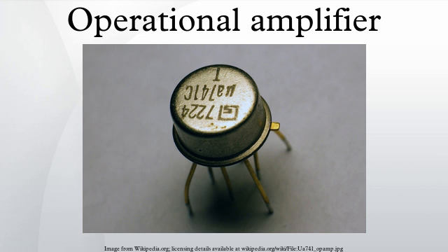The μA741 was extremely similar to the LM101 except that Fairchild's facilities allowed them to include a 30 pF compensation capacitor inside the chip instead of requiring external compensation. This simple difference has made the 741 the canonical op-amp and many modern amps base their pin-out on the 741's. The μA741 is still in production, and has become ubiquitous in electronics. Many manufacturers produce a version of this classic chip, recognizable by part numbers containing 741. The same part is manufactured by several companies.